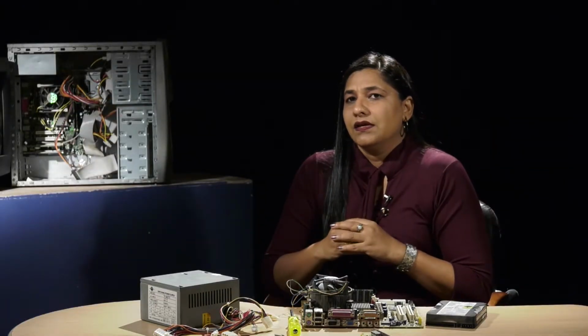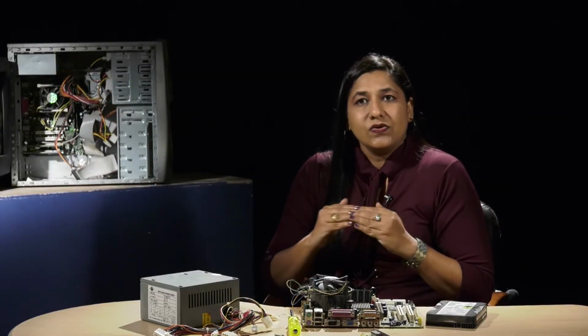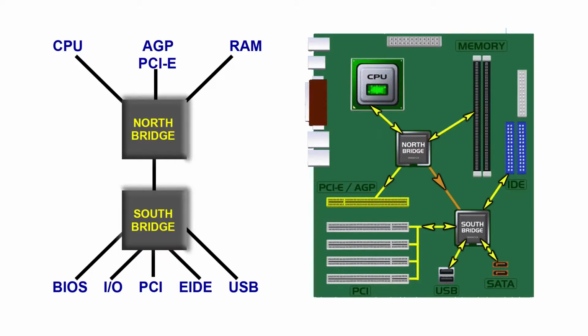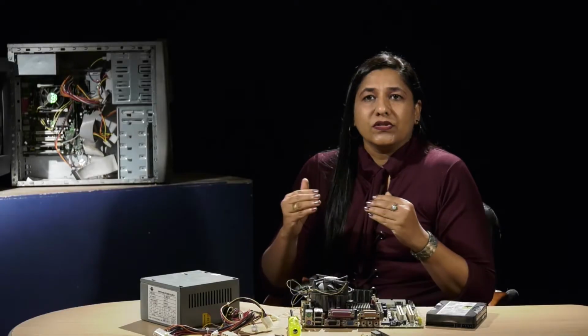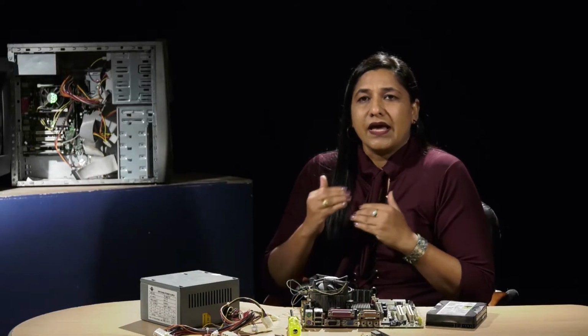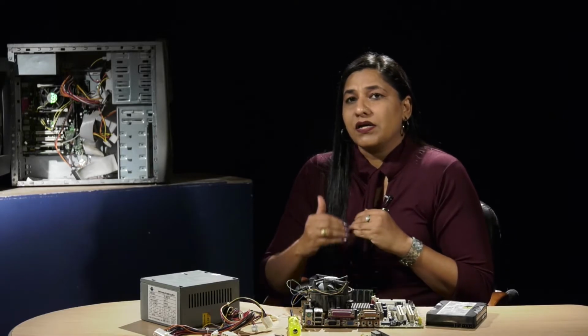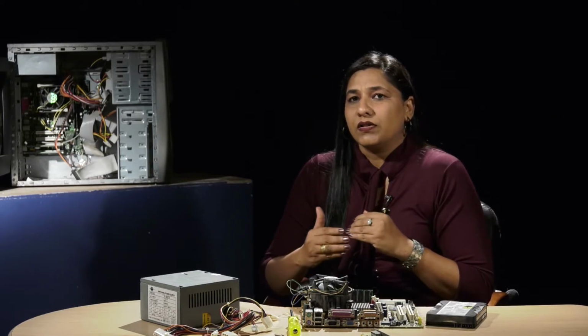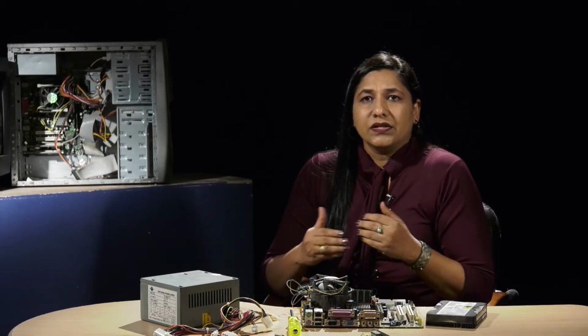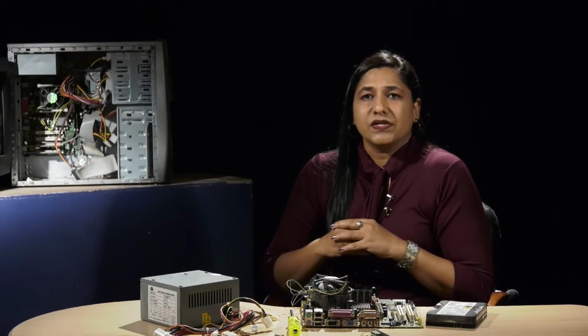Dear friends, kindly note that there is no direct connection of the lower portion and the processor. So, it has to route through the North Bridge. That is why North Bridge is faster than the South Bridge. Both these north and south bridges have to communicate with different parts of the motherboard using buses which act as pathways. A motherboard contains several types of buses which vary in speed and bandwidth.